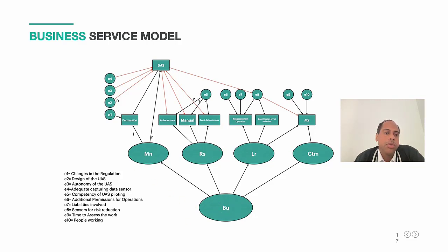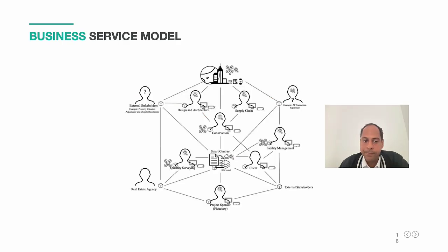It depends if it's going to be more suitable to have one contractor doing the drone work, or to incorporate a drone in your own construction site. If you're going to have more than 10, 20 operations per year collecting data with the drone, then it's most welcome to have a drone in your construction site. If not, it's strongly recommended to have a contractor doing that work for you.